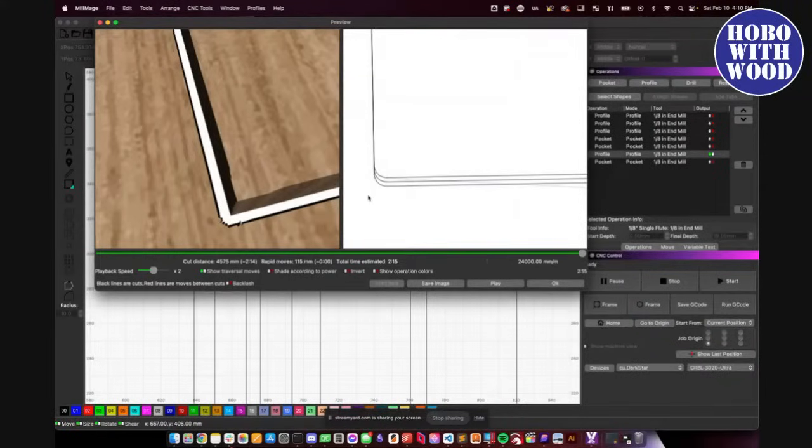Oh, you're right though. The path is rounded too. Yeah, so the path is rounded, but the producing shape is going to be a sharp square corner. And if your kerf offset is set up properly, it will be the same.